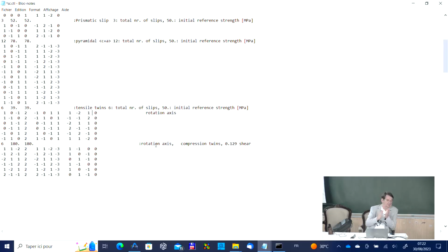A twin is such that, you know certainly a lot of things about materials and crystallography, a specific exact value of shear is needed in a specific direction, and then a given volume of the matrix is switching into the twin position. The same material, individual atoms do not move much, basically, but it's a kind of macroscopic shear, and the whole volume is switching.